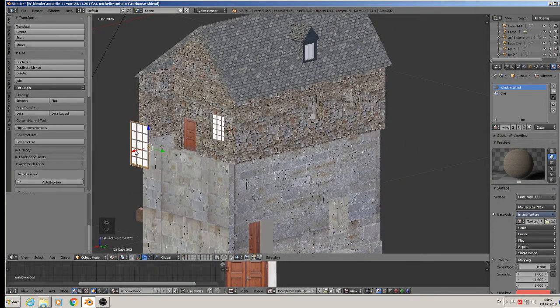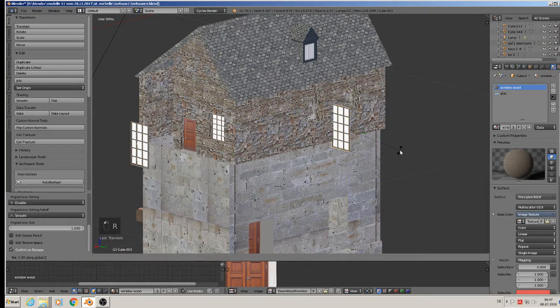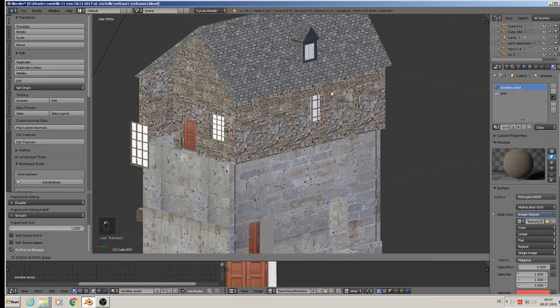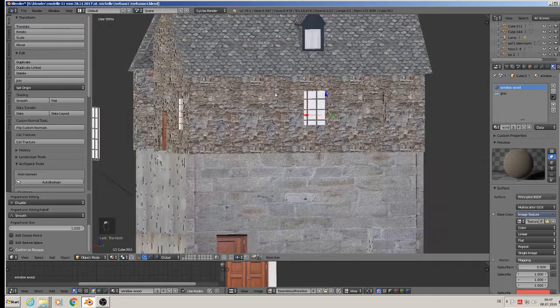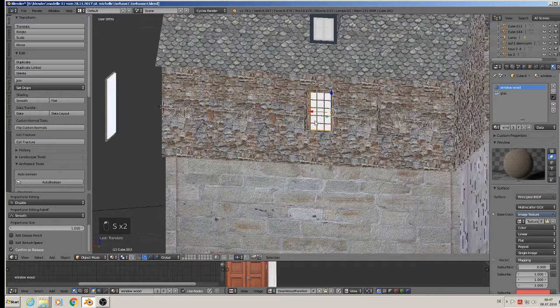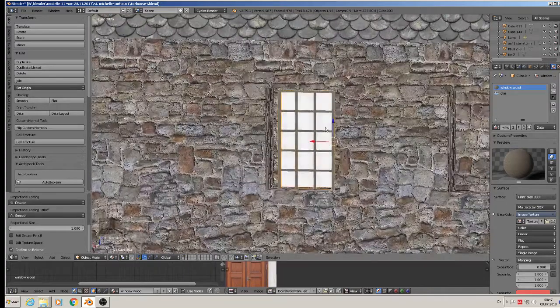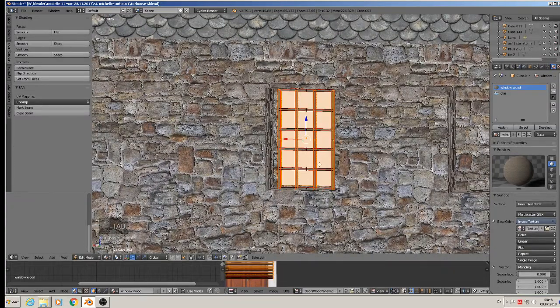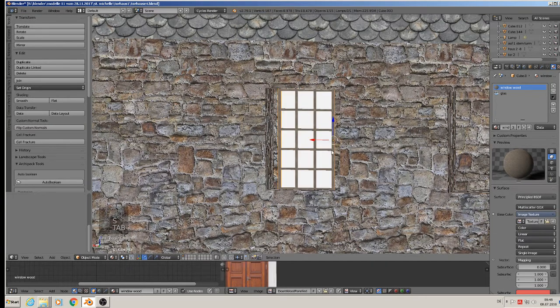Okay, so Shift D, bring it there, rotate set 90 degrees, bring it into, get it up in the middle, and scale down so that it fits. Okay, we have here the same problem that we must scale before.